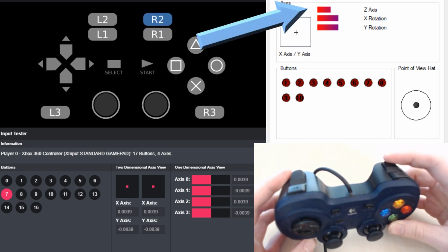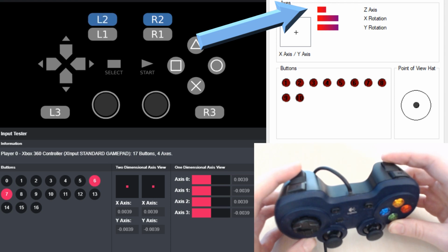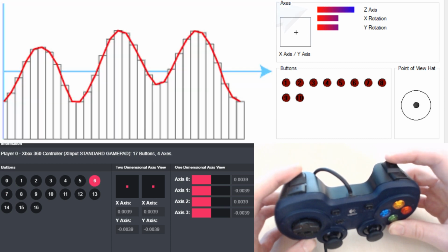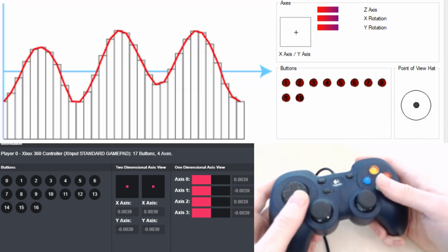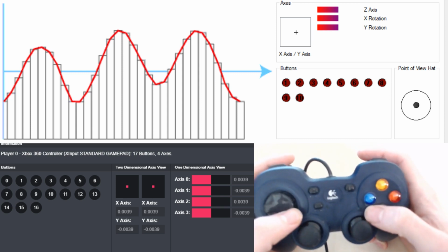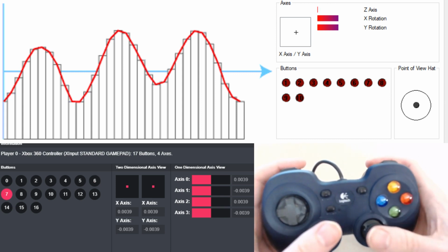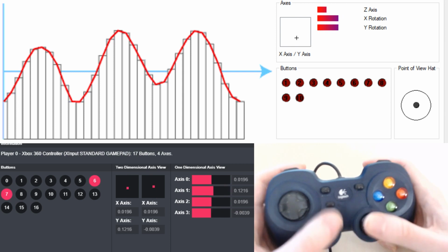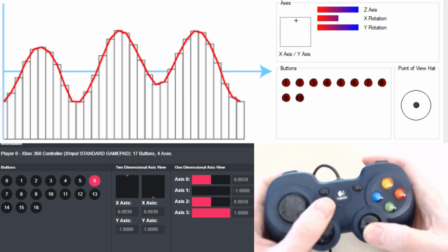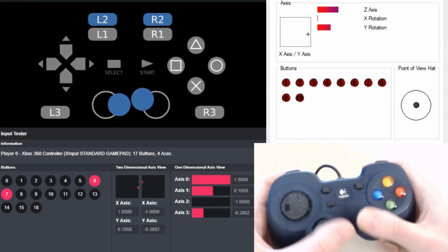So how do computers work with analog signals? The answer is very simple. Every continuously variable physical quantity such as brightness, pressure, temperature, acceleration and so on is first converted into a continuously variable voltage. This step is what a sensor does. Afterwards, this analog voltage is approximated by a sequence of low and high voltages representing a digital number whose value is proportional to the analog voltage. This translation process is called analog to digital conversion, or ADC for short.